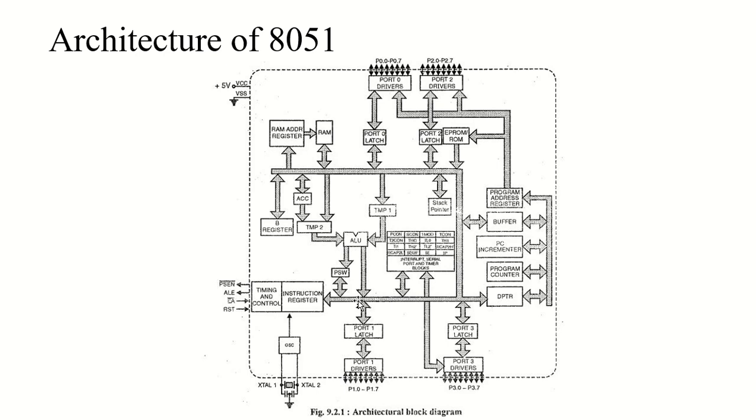In the same way, the PSW contains math flags which the user can use and program in different ways, right? And the user can also use register selection bits that identify the register bank, and they can tell you which register bank is currently in use.